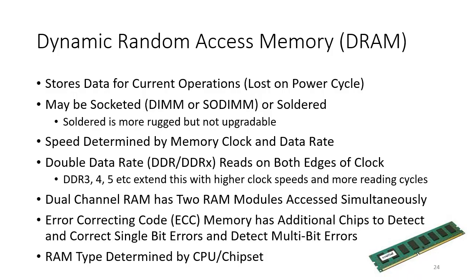Of course, for a laptop, soldered RAM is also lighter because you haven't got any additional components. You haven't got the additional PCB that the memory is mounted on. You haven't got the socket that's required. So it reduces the amount of space required and the weight. But for an IPC, the key point there is about ruggedness. Now, socketed memory, of course, that gives you the benefit of upgradability.